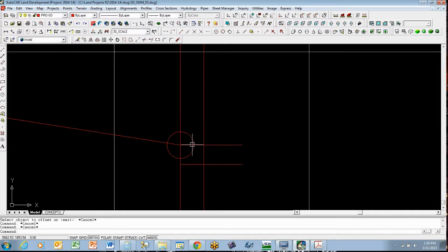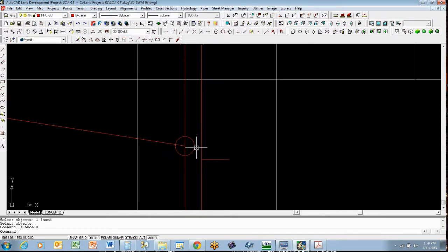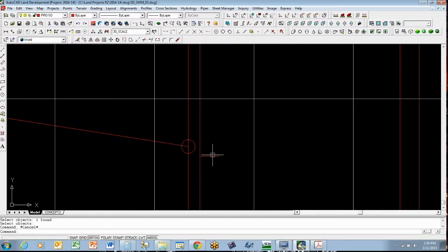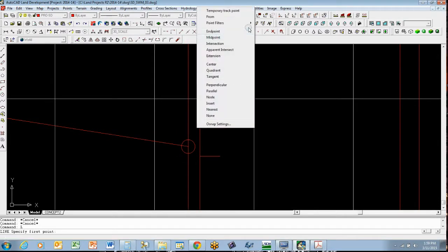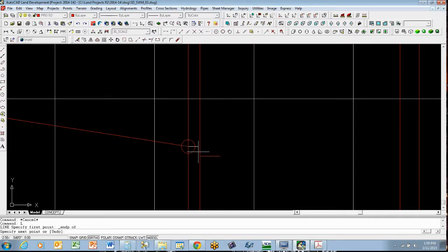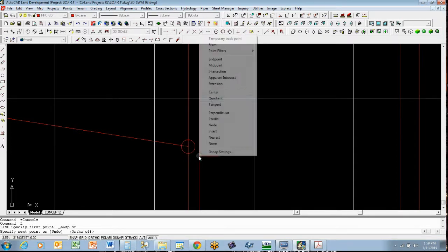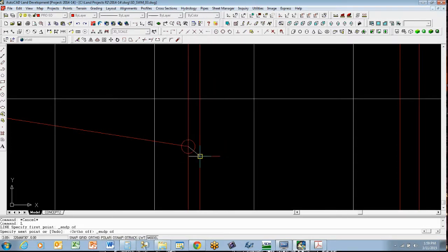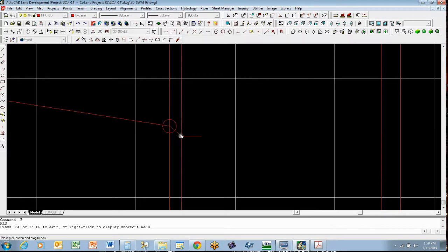Okay. Now that becomes our new bottom of the pipe. And what we do, we always draw the bottom of our structures such that the structure itself is accounting, that's just that we account for the grout that we put in the bottom to go from invert in to invert out. Okay.